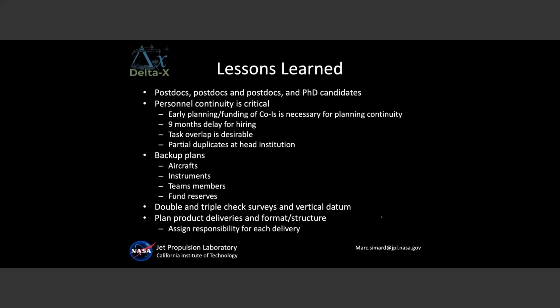We've been having a lot of issues with vertical datum using different data sets, whether from USGS or LiDAR companies. We've been struggling with the vertical datum, the epoch, and which geoid was used, which is incredibly complicated.